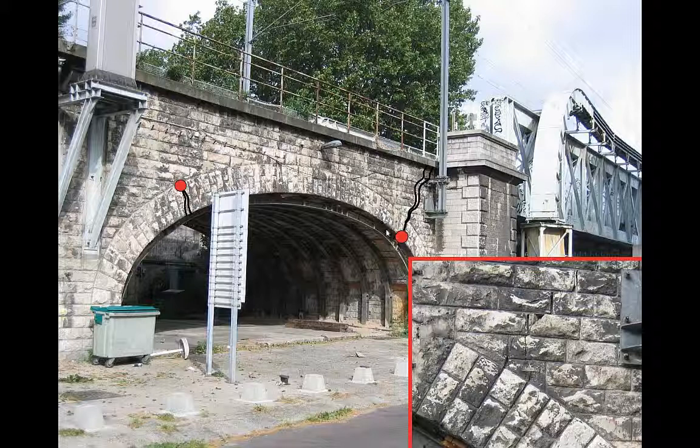And you can see on this next slide the river crossing, so it's a girder span, a rather large abutment at this point. That abutment isn't founded simply on timber piles. There are caissons there, so there's no chance of that moving.